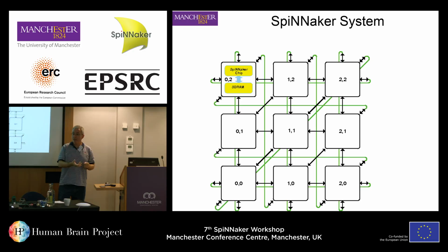While conventional supercomputers are actually quite inefficient at simulating those kinds of systems, they're used to transferring big blocks of data reliably from one place to another. SpiNNaker is very good at sending very many messages in parallel, very short messages, spike or no spike, right across a large array. And so that is very efficient for power, and it's very well suited for neural network simulations, which is the philosophy behind the design of SpiNNaker.